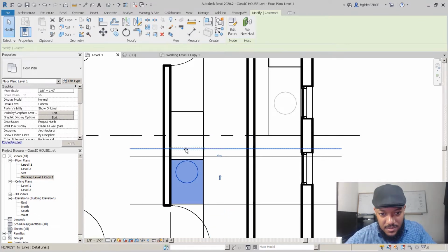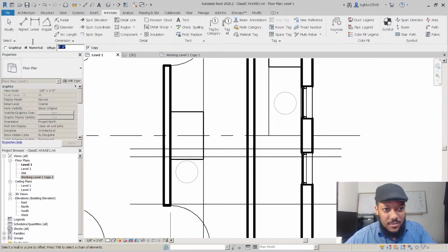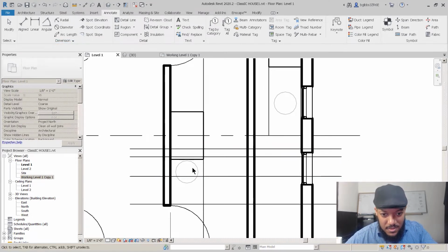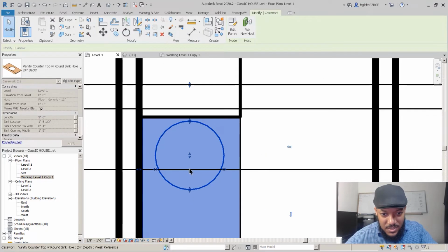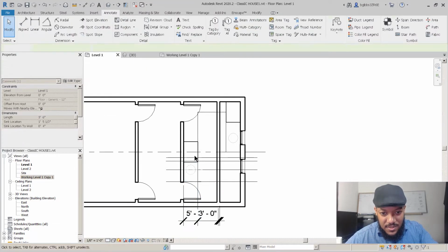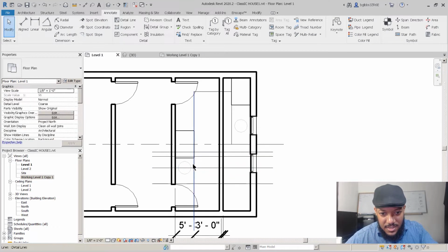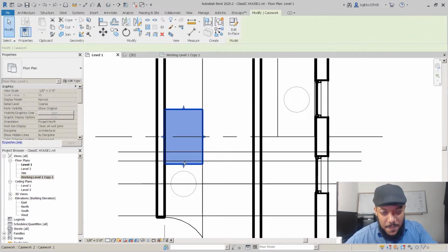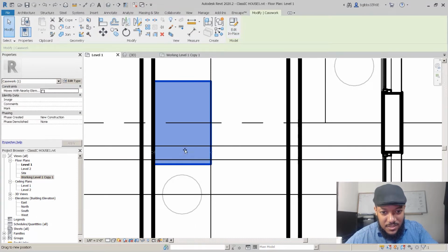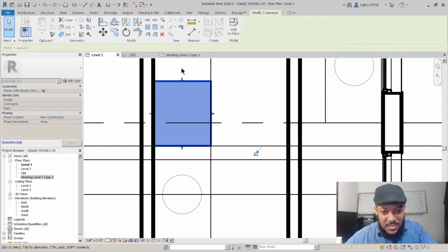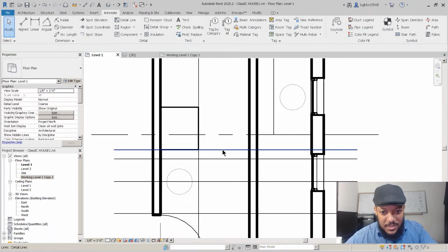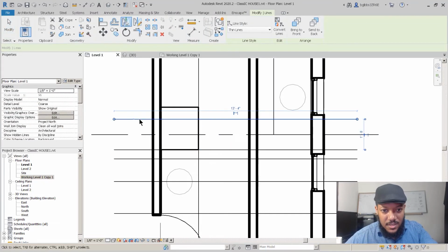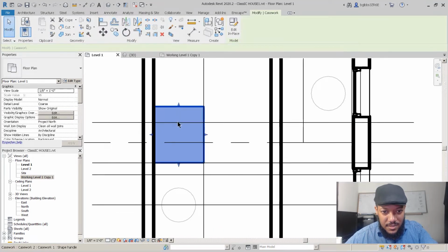And so now we can just move down 21 inches to get the middle where our sink would be. We just move that straight down. And now we're going to change the size of our little tall cabinet. We just want to move it, and though it's an edit in place component, you can change the grips. You can't change the footprint unless you go in and click edit in place. And we're going to mirror, pull this all down.